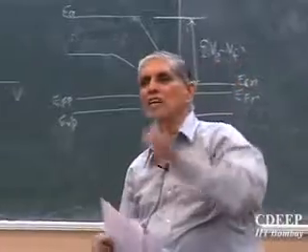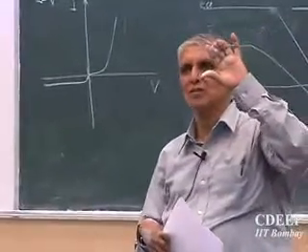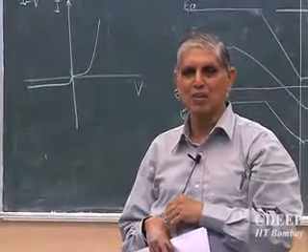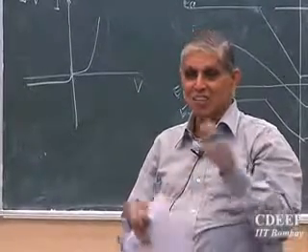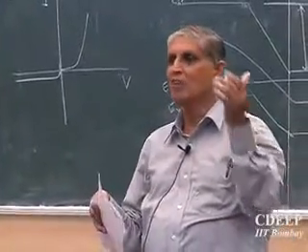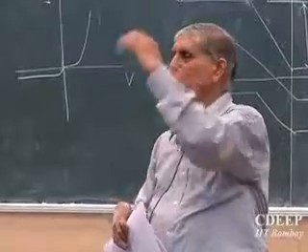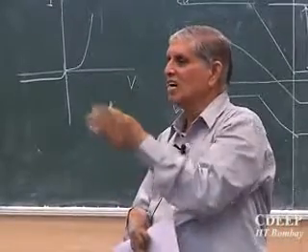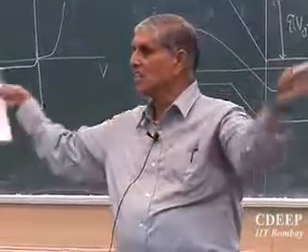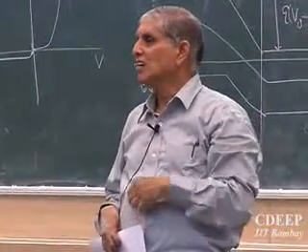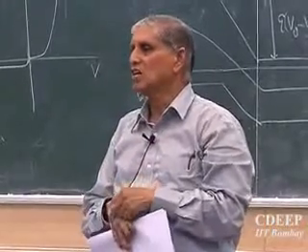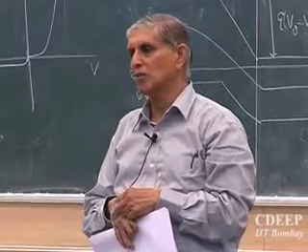Now electrons find a lesser height to climb. Holes find a lesser height to climb. So they start diffusing again. Is that correct? Initially there was no carrier motion. I connect forward bias, I find the barrier reduced. So holes from P start moving towards N, electrons start moving from N towards P, and since there is a battery terminal, these carriers will be collected and current is maintained because the battery can keep charging. So a forward current can flow as soon as I apply forward bias.